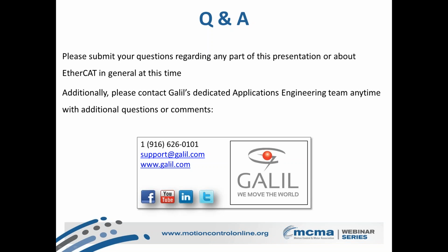You can certainly put gigahertz processors on your motion controllers and your EtherCAT drives, but we have to remember that these are controlling physical systems, and if the motor in your system has a bandwidth that can only respond to a command, say 50 or 100 times a second, there's really not much point in telling that motor to move 1,000 times a second. It's not going to be able to respond. So there may be plans in the works somewhere for gigabit EtherCAT or Ethernet, but at this point, I think the applications for which it would be appropriate would be few and far between.